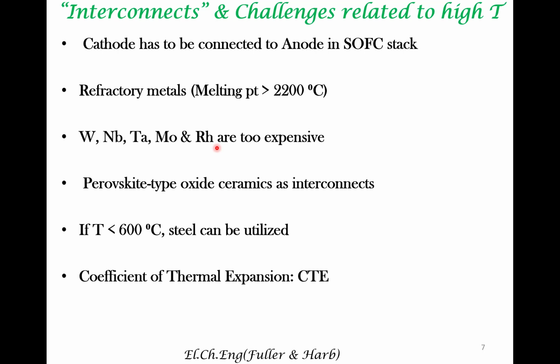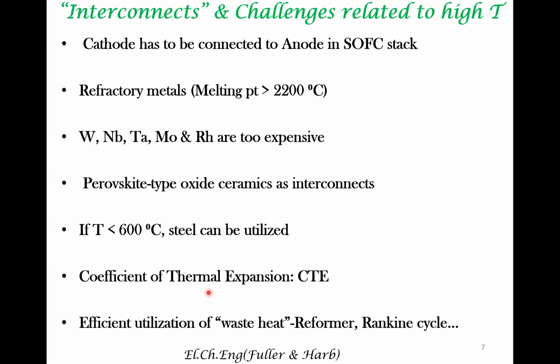Again, an important challenge whenever you are thinking about SOFC is compatible coefficient of thermal expansion of the three components. The anode, the electrolyte, and cathode should have compatible or comparable coefficients of thermal expansion so that the thermal stresses associated with changes in temperature are not significant.